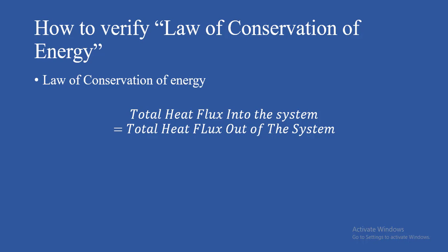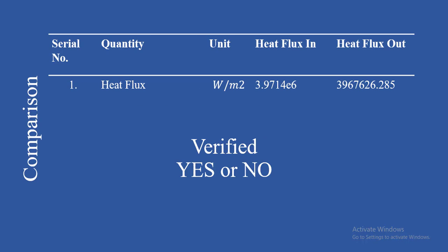We will verify the law of conservation of energy. There is no direct command in ANSYS Workbench to determine the law of conservation of energy. So what we will do, we will determine that the total heat flux going into the system equals the total heat flux going out of the system. If these two are balanced, then we will obtain the required result. We will again compare the results of heat flux going in and the heat flux going out.